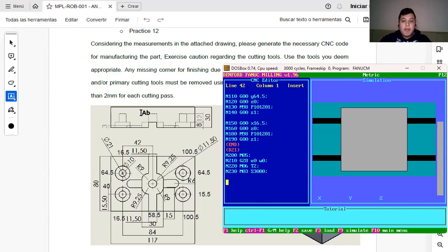And we're going to repeat the same points for this. Now we're using the same subroutine, but now it's going to pass only 4 times because here we have 8. So each coding pass is going to be 2, 4, 6, and 8. So you're going to repeat 4 times. So we have to go to the first point that we wrote. It was x 60.5, y 15.5, and z 1.